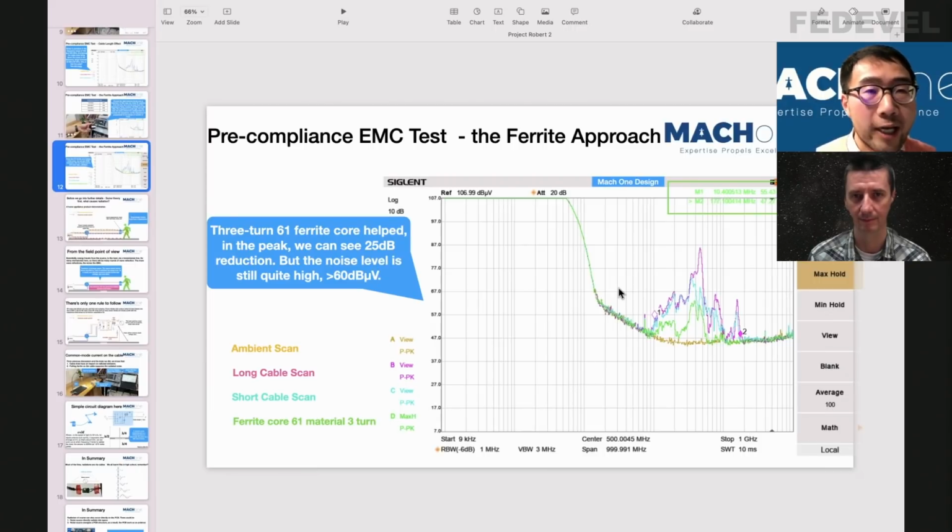In some particular cases, where you have two systems connected by a cable, and one system is working at one frequency and the other system is working at double that frequency, then it is very tricky to decide where to put the ferrite in the cable. I can't remember from the top of my head, but I remember if you put it in the wrong place, you actually see the noise increase. But generally, when you place it further from the source, you will not get as good results as if you place it close to the source. Yes, because when you put it too far away, the energy has already leaked into the space, basically. Okay, so let's have a look at what happened.